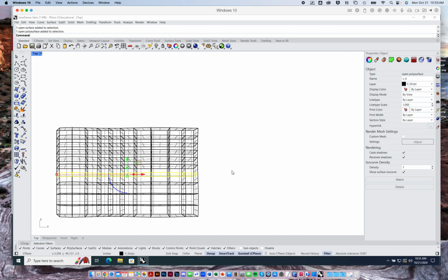You can then see how it works, get the feel for this, go through the steps and motions, get some chipboard, look for the 1-ply, make sure that it's flexible, it'll flex and give you some bend. And then run this again with that material thickness. And then sign up for laser cutter time. Go to the Fab Lab, go to the laser cutter and sign up for some time. Right? Probably need about half an hour, I would guess. If you're not sure how much time you need, you can always show them your files and say, how long do you think this would take? And they can maybe give you a better ballpark than you might if you haven't done it before. All right? Does that help a little bit?